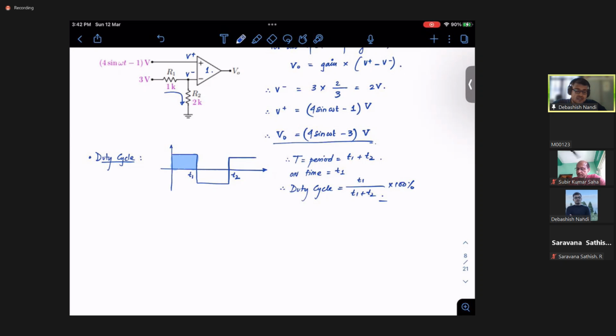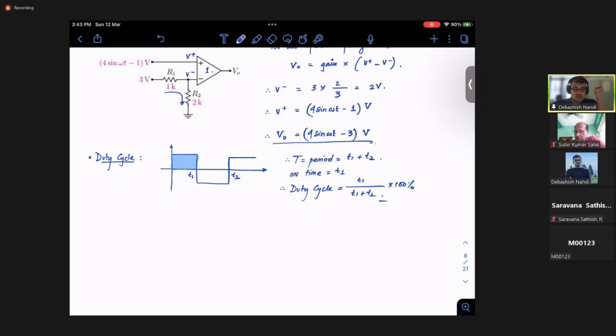So this is one way, and now the question is why it is called duty cycle. In factories, or a simple example, if you see any security guards of your colleges, they generally work in shifts. Suppose you have 24 hours in a day and they work in 8-hour shifts. One person will work for only 8 hours. They have morning shift, day shift and night shift, right? So suppose they work one shift, what will be their duty cycle? Their duty cycle will be nothing but 1 over 3, because they are on duty for 1/3 of the entire time. So their duty cycle would be 33.3%. This is to make sure that you never forget how this term comes about, and you don't jumble it up with on by off or on by on plus off. It should be how much time you are on duty, or the signal is on, over the total time, right?